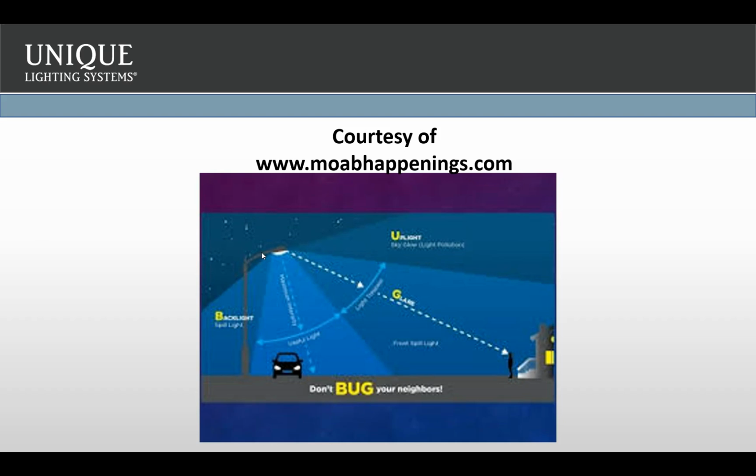One of the things that we've done in the past is set up a demonstration kit at someone's location to show whoever the governing board is that this isn't affecting the dark sky. We're not putting any glare out there. We're following the BUG guidelines as closely as we can. It is low voltage, so we don't have a 1,800 lumen street light that we're dealing with. We're dealing with a 300, 400, or 500 lumen type fixture.